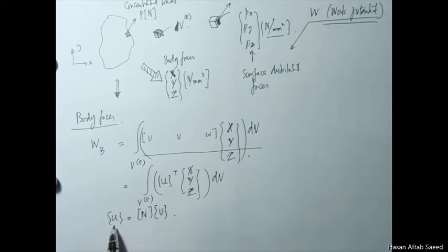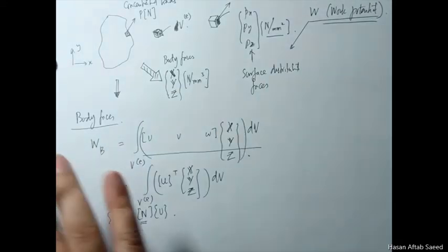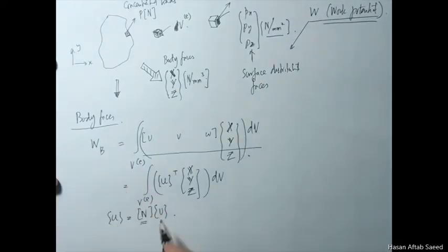Now also recall from your previous lectures that we have a very convenient expression for the general displacement vector, and this is the N matrix which links the nodal displacement. This is capital U, this is small u. So capital U means the nodal displacement. We need everything in nodal displacement. This is FEM. We are converting everything from general expressions to the nodal values.